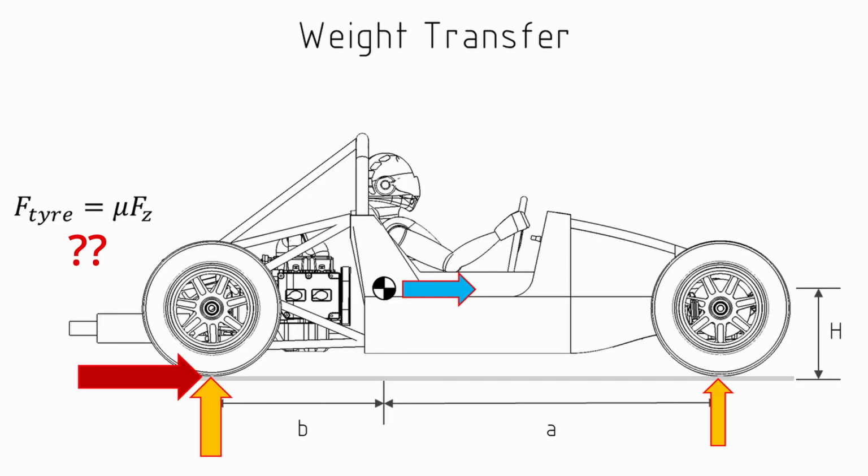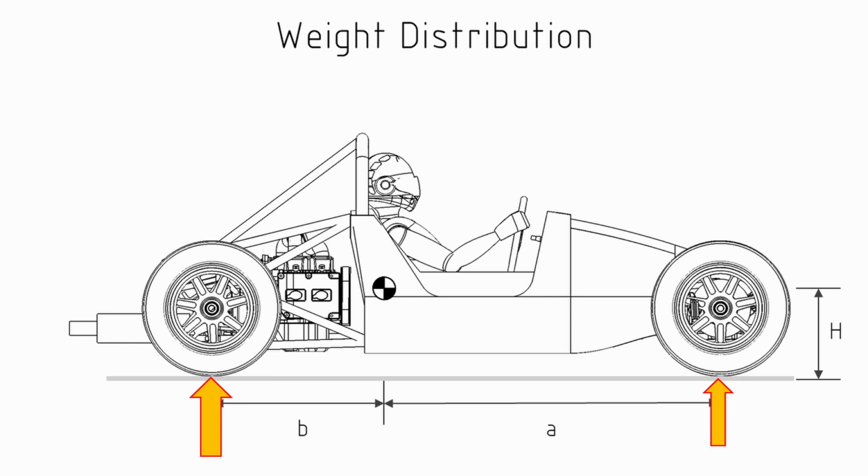And in fact, even if we had good tyre test data, that coefficient of friction would be different for different surfaces. So we could really only do that test on the surface we're expecting to run on and do the calculations based on that. We also, for the design of the vehicle, at the early conceptual stage, don't even know the expected weight and weight distribution of the car. So that means that this simulation isn't going to provide a super accurate result.